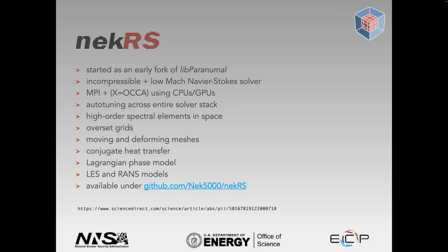We're still using MPI for distributed computing, but now there is this component X, which is the accelerator or the CPU. So the code is not just limited to GPUs, you can also run it on CPUs. And our abstraction for this is called OCCA. I'll come to that in a second. We auto tune across the entire solver stack, and it's using high order spectral elements in space. And it supports various models for moving the mesh, deforming the mesh, conjugate heat transfer, Lagrangian phase model, turbulence models. And all this is available under our GitHub organization. And as I said, it's open source.